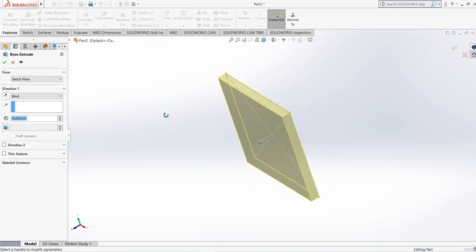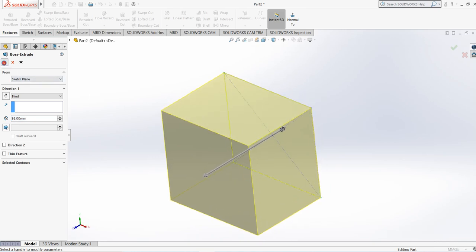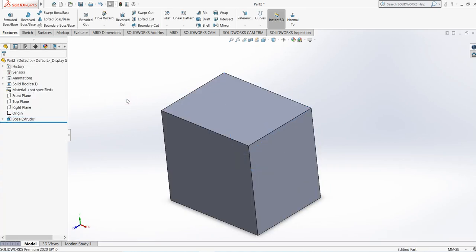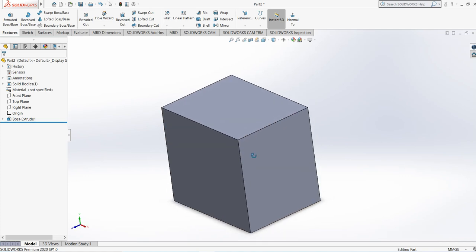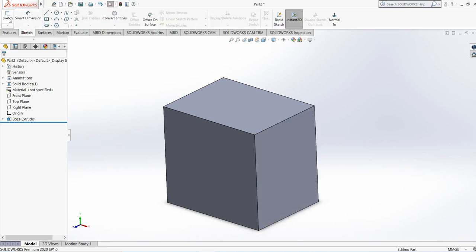See, extrusion is a very important tool, as well as this revolve tool is very important, because any structure which is revolving, which has a circular geometry, and is symmetric to both sides, will be like a shaft. We can use this revolve tool for a shaft, or any cable-like structure. Okay, so let's just go for this sketch.